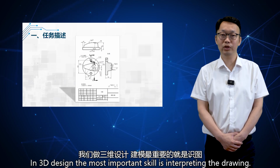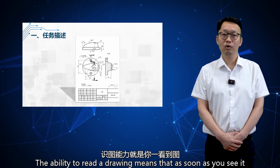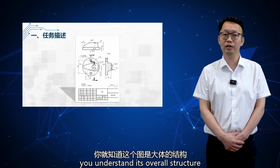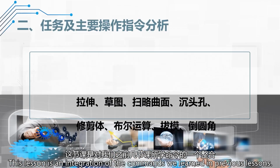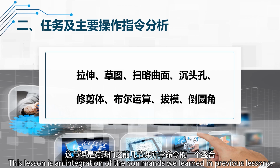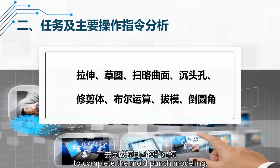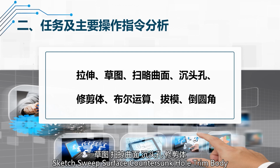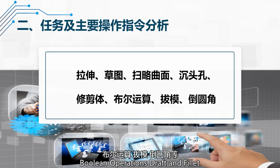In 3D design, the most important skill is interpreting the drawing. The ability to read a drawing means that as soon as you see it, you understand its overall structure, features, dimensions, and how it's assembled, and so on. This lesson is an integration of the commands we learned in previous lessons. We need to use the commands we studied earlier to complete the mold punch modeling. The commands we will use include extrude, sketch, sweep surface, countersunk hole, trim body, Boolean operations, draft, and fillet.